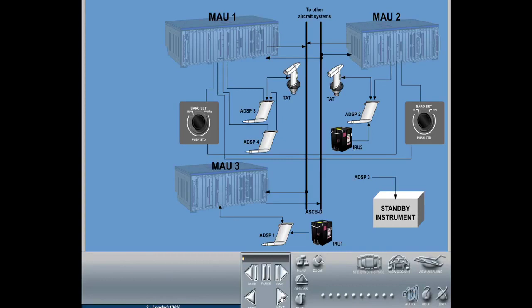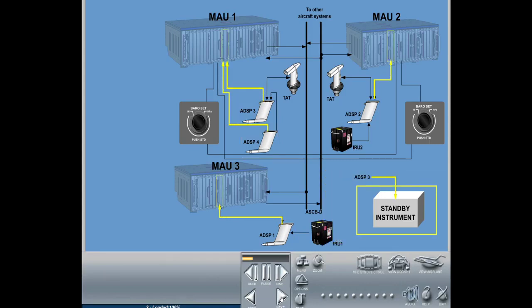The ADC performs air data pressure calculations, which are forwarded to the Air Data Application resident in MAU, or to the Integrated Electronic Standby System for airplane fuselage effects, and sends the information to the flight deck to be displayed as airspeed, altitude, Mach, and angle of attack.